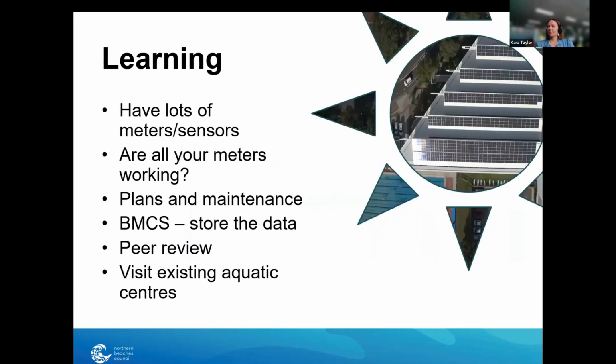So quickly, I'll just rattle off a bunch of learnings, because I think I'm getting close to my time, but I have heaps. I'm happy to share with anyone who needs to shout out. But engineers love data, the more the better. Check that your data is coming through now. Your meters, your sensors are working and they're capturing data. How long does your BMS store data for? You may want to go download it. I didn't realize ours gets chucked every 12 months. It's not stored. So go download it, so you can have a longer data set.